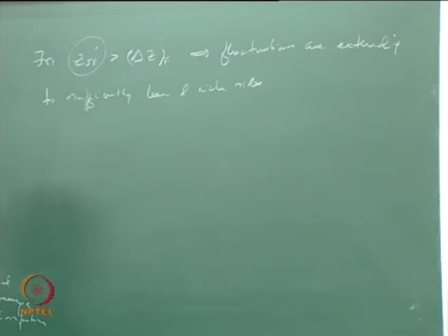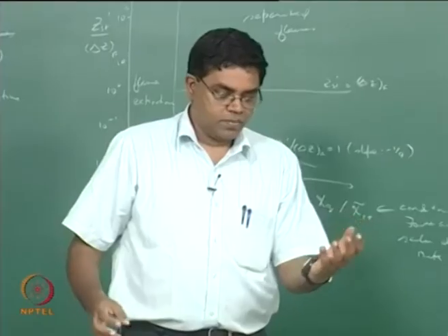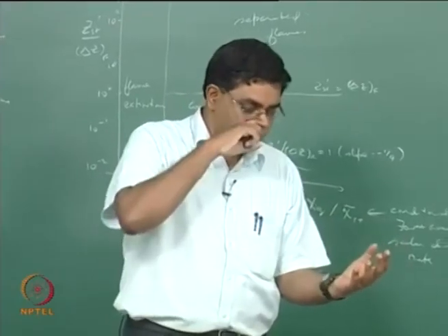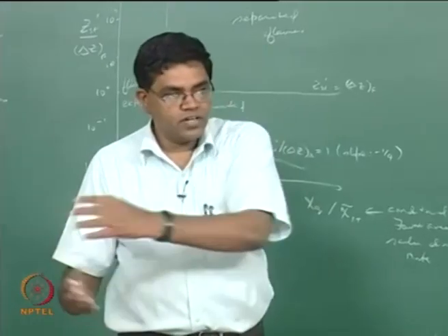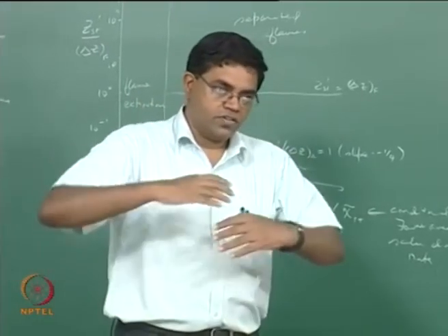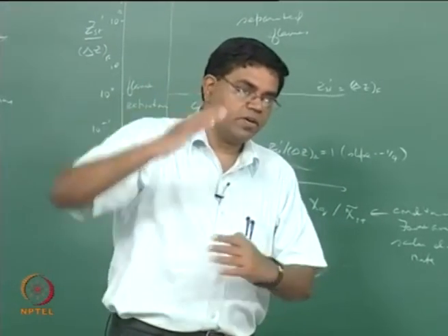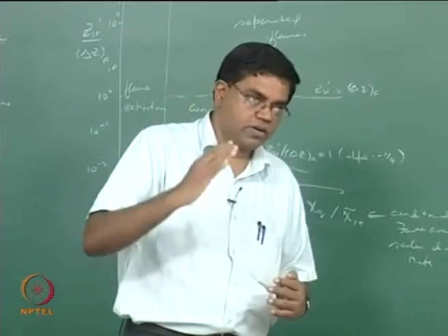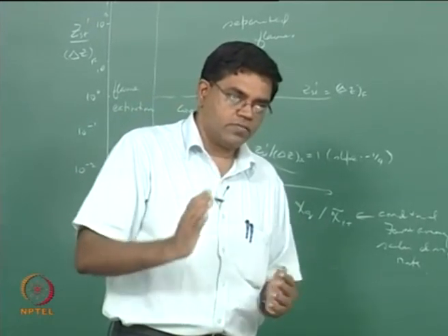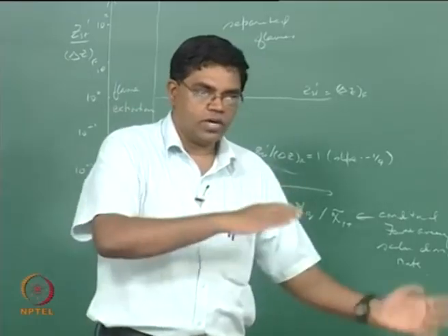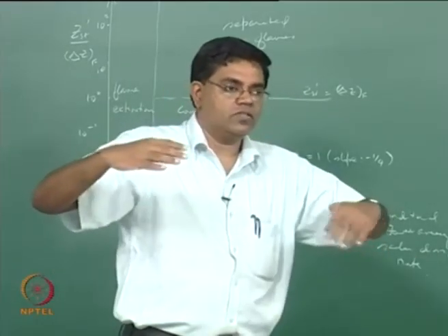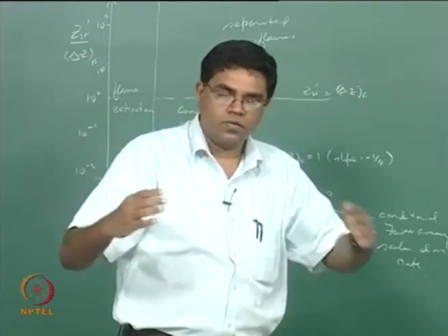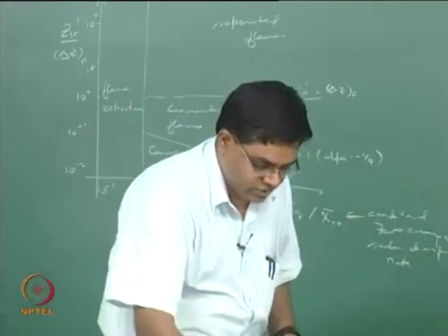and therefore what this means is that the fluctuations are causing some amount of the lean side of the flame to go to the rich side and vice versa. So this begins to separate the flames, because the flames are effectively dictated by what's near the stoichiometric surface for the reaction zone, and if you have these things going on, you will create intermediate regions of stoichiometric surfaces, so the original flame is essentially broken.